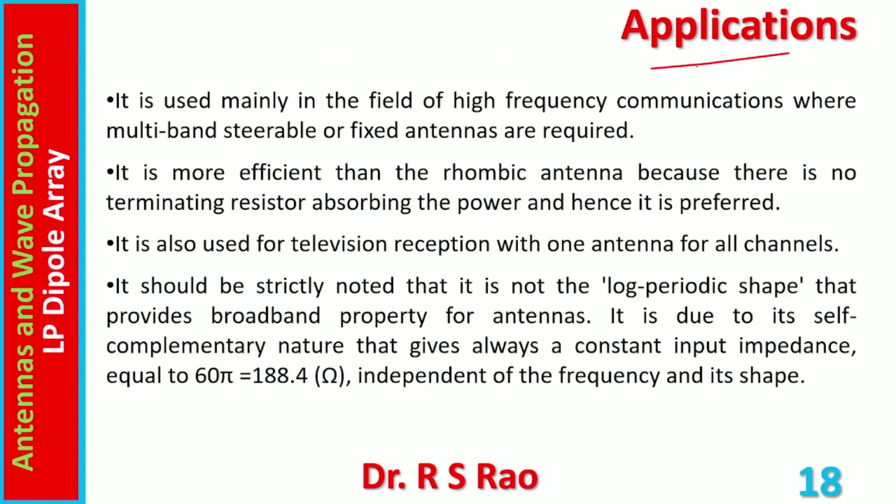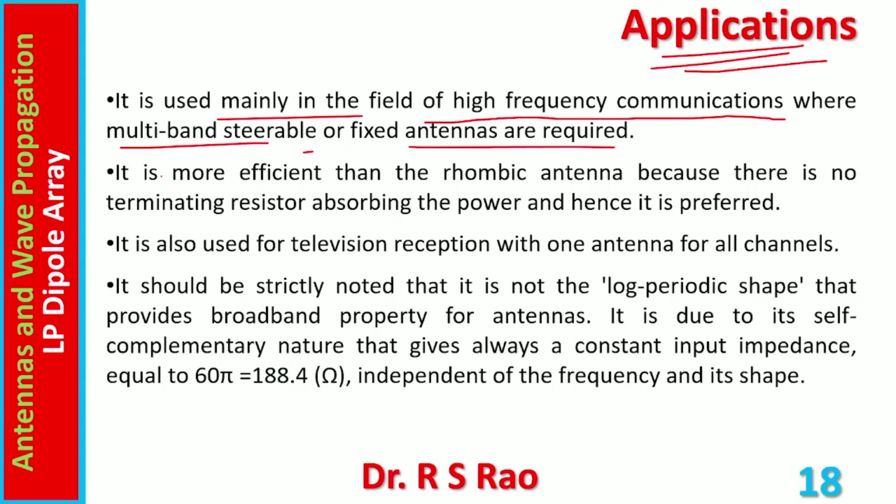A few points regarding applications. It is used mainly in the field of high frequency communications where multi-band steerable or fixed antennas are required. It is more efficient than the rhombic antenna because there is no terminating resistor absorbing the power, and hence it is preferred.